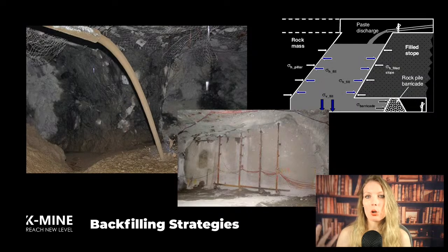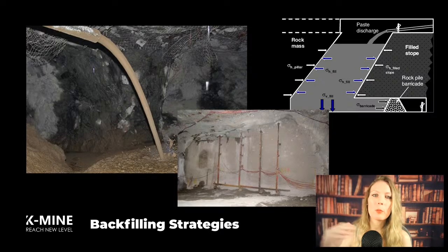And the application of empirical methods such as Matthews stability graph, numerical simulations for stress analysis, and financial modeling techniques such as NPV or ELOS provides a robust framework for stope design.